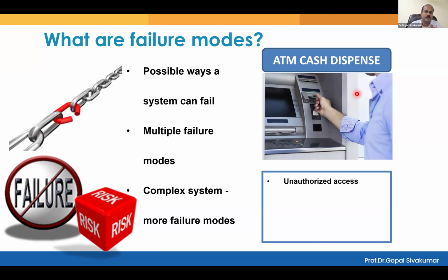Right? Once you are exercising the FMEA, slowly, failure modes will keep moving away. And then only the failure modes which are currently troubling you will be part of your FMEA table. The lesser it is, the better is your process. Right? So that's how everything is a part of your continual improvement journey. In the initial stages, there can be 100 failure modes, but after a span of 6 months or 1 year or 2 years, the 100 failure modes can be brought down to just 4 or 5. Things become manageable, right?